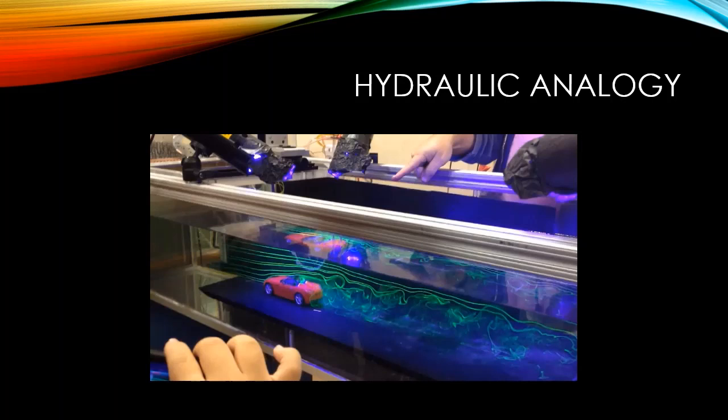So in previous cases also we have seen mass flow rate, that is the continuity equation as well as the momentum equation. We haven't used the continuity equation for the Hele-Shaw apparatus, since it is maintained constant, so it is left. We are considering only the Navier-Stokes equation. Similarly for the electrolytic tank, we are considering only potential flow. So we are just plotting the potential lines and the stream lines for any kind of arbitrary models, right?